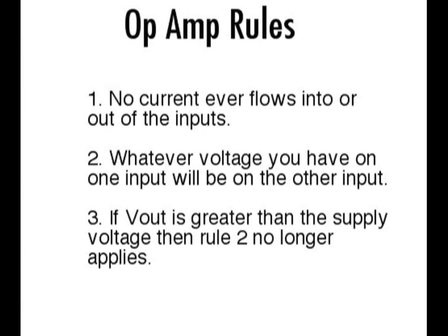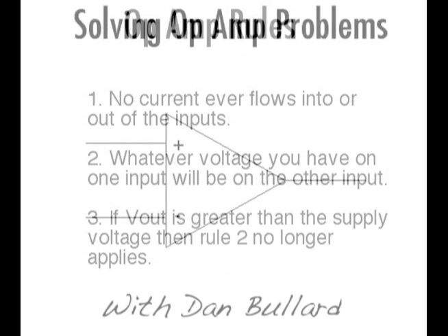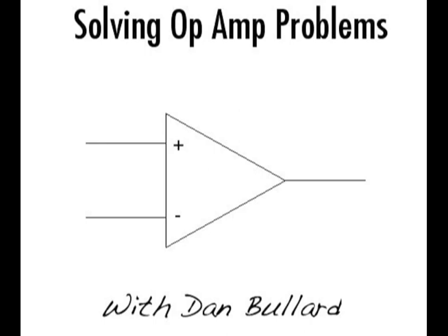No current ever flows into or out of the inputs. The 2 inputs will always be the same voltage unless you calculate a V out that is greater than the supply voltages. Deal with Ohm's law, Kirchhoff's law,